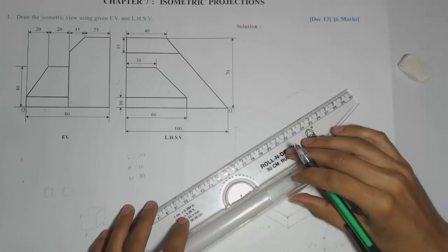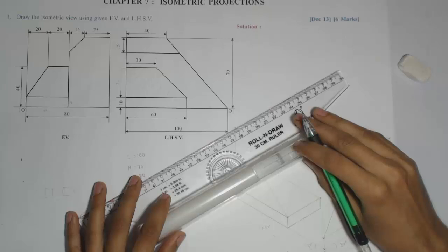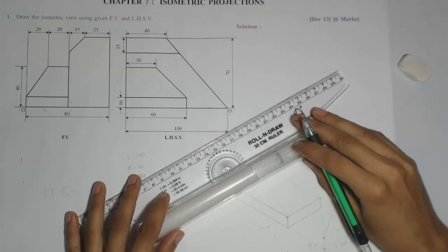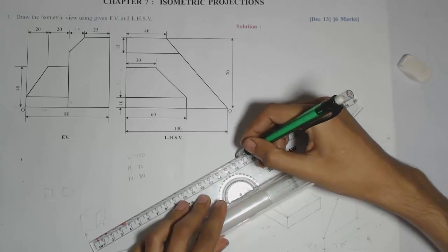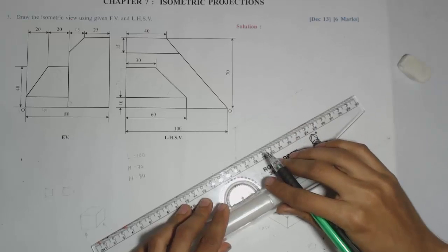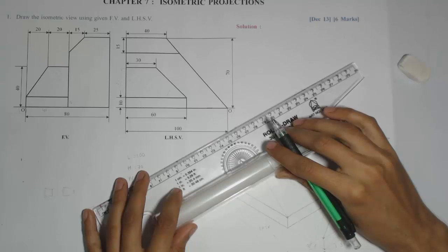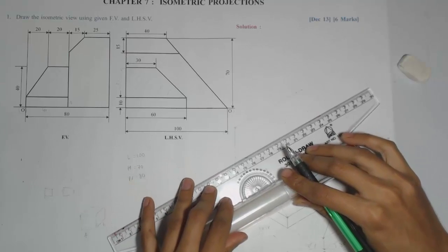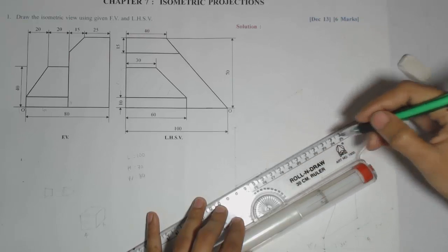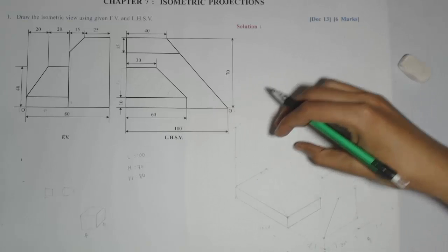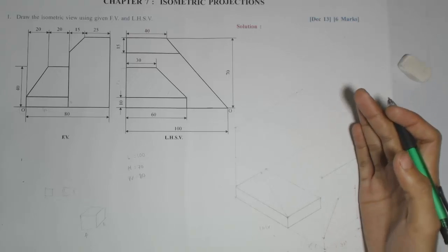So we'll first mark the projectors from the highest points to get the top view, because the projector from the maximum height will give the top view. From the bottom you need not draw those projectors because that view may not be visible to the observer. So first preference I'll give to the projectors from the highest points, because that will give me a top view which is obviously visible to the observer. Again, no need to produce along the entire width, because this part is only up to 40, width of 40.